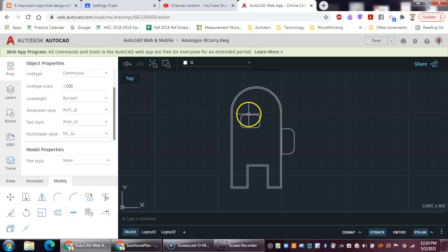So I'm still going to offset this tool here and this tool here. Let's go back, left click on that offset. I'm going to select here, and we're going to offset this going to the outside by 50 thousandths, 0.05. I hit enter to drop that in place.